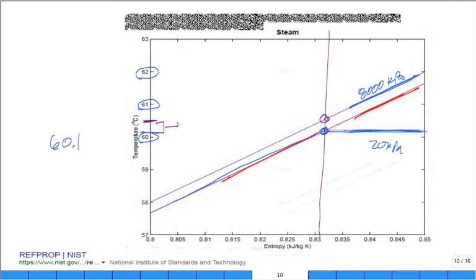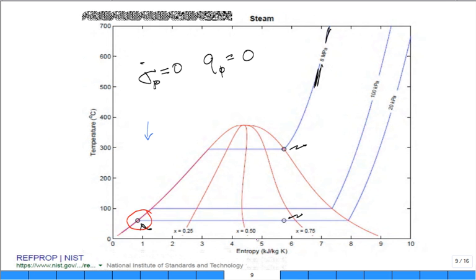And this is one of those parts where you'll find faculty, and I think a lot of you already knew this, but they'll say, you know where? They're at state 4, I'm sorry. And what will they do by putting state 4 so far away from state 3? They'll make it clear that state 4 is in that vicinity. But they've grossly exaggerated the temperature at state 4. The temperature at state 4 is essentially the same as the temperature at state 3, plus a little, half a degree. True? Do you see that?